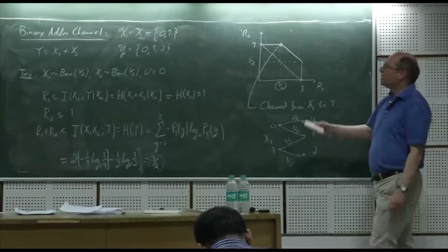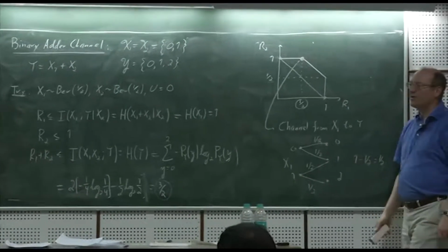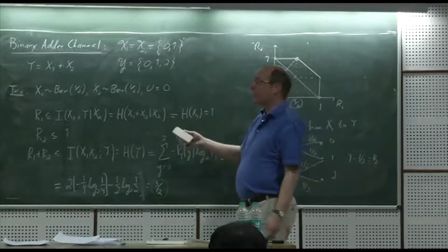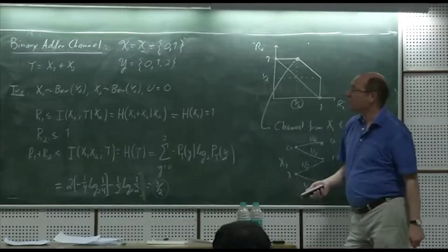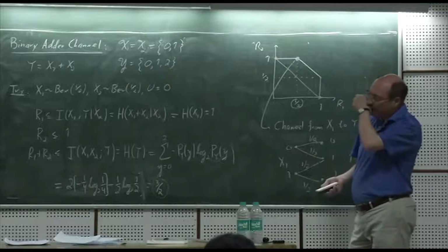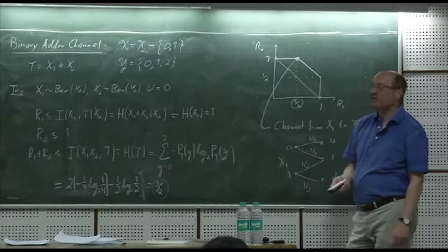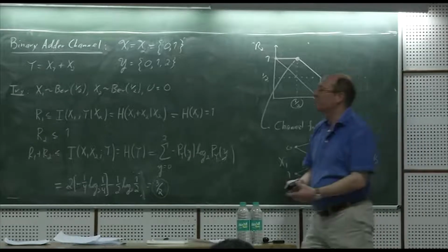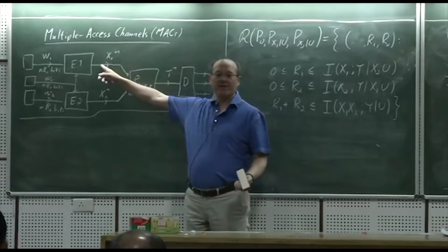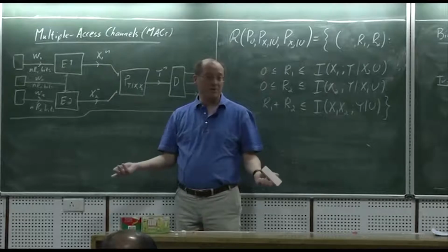about this. So let's now go to the more interesting class of channels we want to discuss in more detail. Those are the Gaussian channels. The Gaussian channels are very rich for this problem. Very nice because we have a capacity result. And we want to look at ways of getting to capacity, and it's also really interesting because it's very practical, right? I mean, many mobile stations transmit with only one antenna, right? And so the scalar Gaussian problem is really interesting.